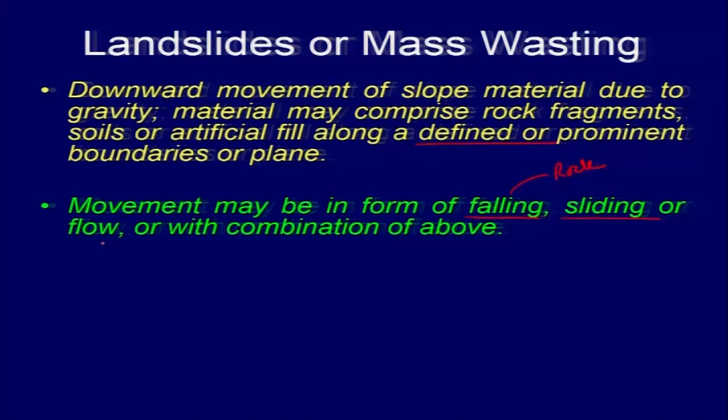or it may be in the form of flow, or with a combination of all three also. If you are having a fall, then it is mostly in areas with rock blocks sitting loose. Then we may have a fall, we may have a slide, as I told, if you are having even the bedding plane, or the material is fractured or jointed.